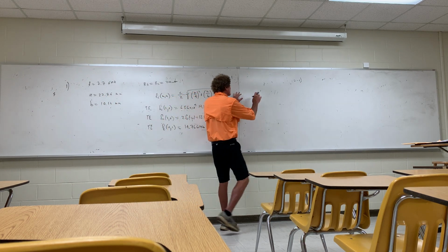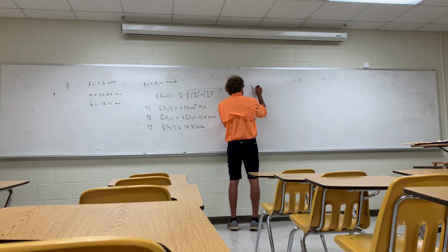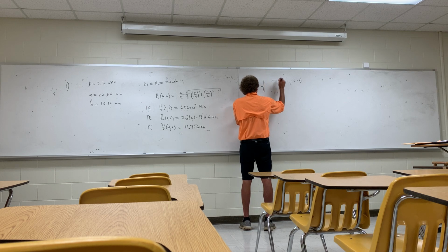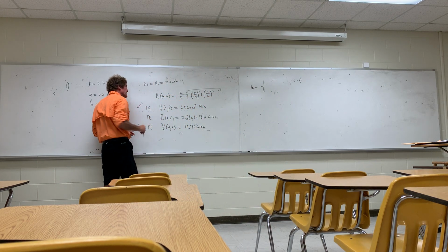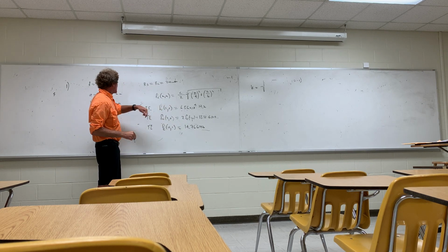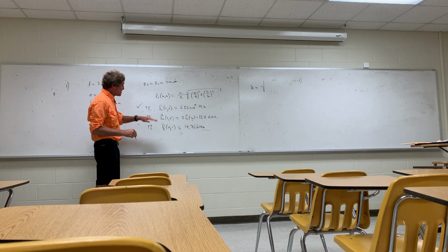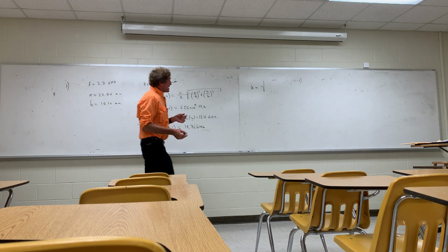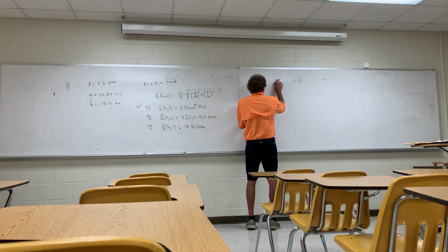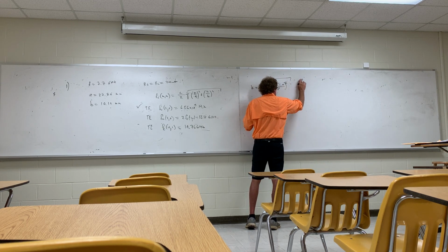After that, the next thing you get is K. And K is going to be the square root. Well, first of all, let me say this. What mode propagates? Only one, this, because that cutoff frequency is less than 7.7 gigahertz. The other two modes are higher than that, so only one mode propagates as expected. That was predictable. Therefore, K is going to be equal to the square root of 1 minus quantity FC10 over F squared.